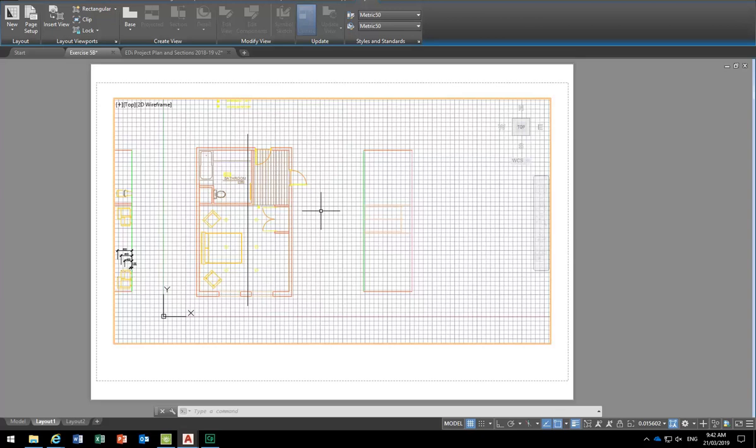And do you have an idea what scale this plan should be, Quinton? Yeah, exactly. That's good. If you're thinking 1 to 50, that's right, because for interior design, 1 to 50 is almost the standard scale. I was going to ask you about that. How does it get chosen? Oh, it depends on the size of the space or the drawing you're doing. But for interiors, you want to see a reasonable amount of detail as well. So 1 to 50 is used more than 1 to 100. But sometimes you've got to use 1 to 100. And for architectural drawings, 1 to 100 is more the standard, I suppose.